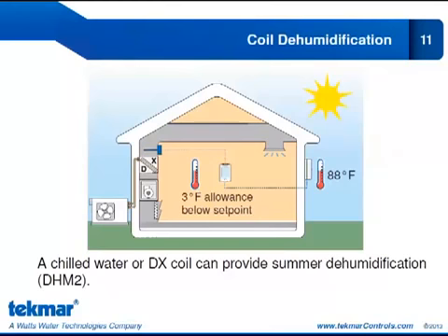So in the event that the duct air temperature nears freezing, the thermostat will remove the dehumidification signal, but the cooling compressor will continue to operate together with the fan operating at full speed. Now this fan operation would be controlled by the air handling unit. It's not controlled by the 553. And that fan will allow the DX coil to warm up. So the freeze protection is available if you install the duct sensor 083, but it is not mandatory. We are going to look at this in one of our applications later in the presentation.